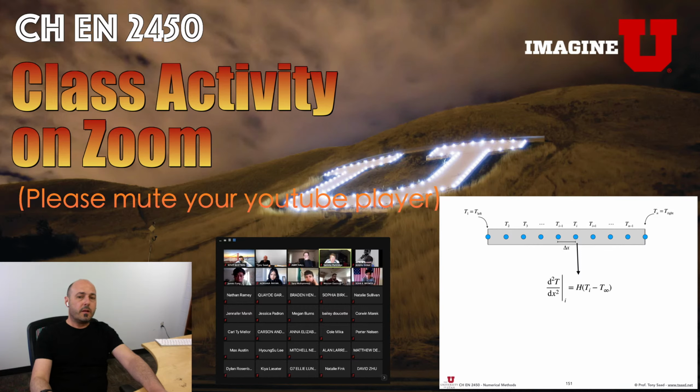Okay, now that the equation is valid at any point in the domain, we're going to take a representative point, point i, and apply the equation over there. And I hope you agree that at that point, the governing equation is d2T by dx squared at point i. So you're evaluating the second derivative at point i equal to h times (Ti minus T infinity).